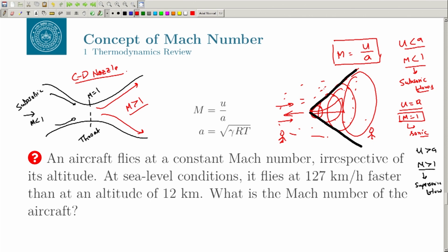So, we got the subsonic regime, the sonic regime, and the supersonic regime. You can also have a hypersonic regime, where the Mach number is much higher than 1, let us say Mach greater than 5. In this kind of case, you may get ions, your molecules may dissociate, and some new molecules may form. So, ionization and dissociation become important, and there are many effects, because you will have a very thin shock layer.